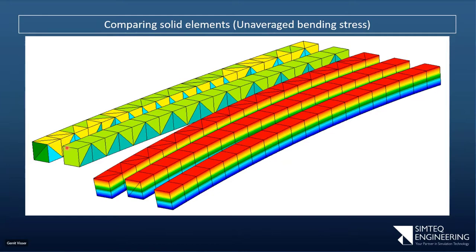You'll still get a kind of weird stress state, but it will start to represent this, even if it doesn't get to those maximum values on the outside. But for these elements, under the perfect case, the kind of stress state, in other words, kind of load as well, that it can represent, a single X element is enough to actually give you pretty accurate answers.